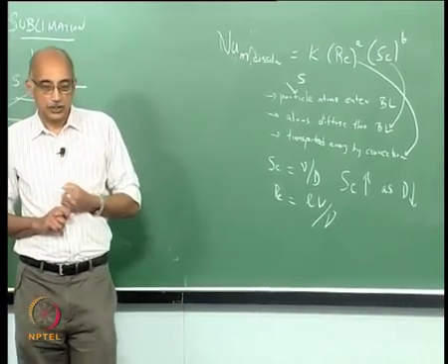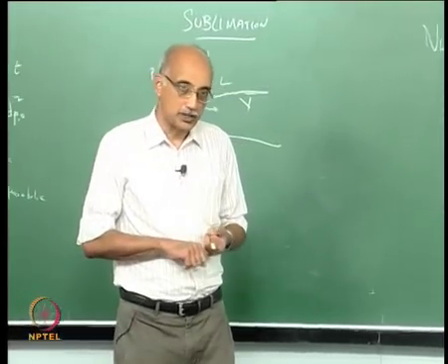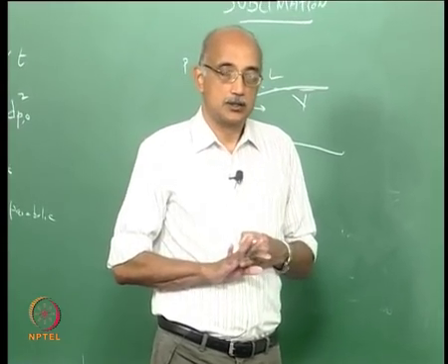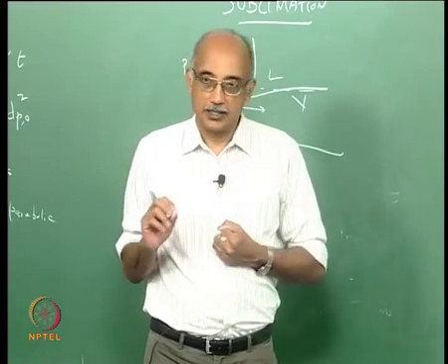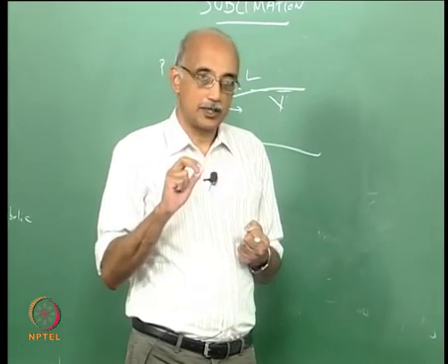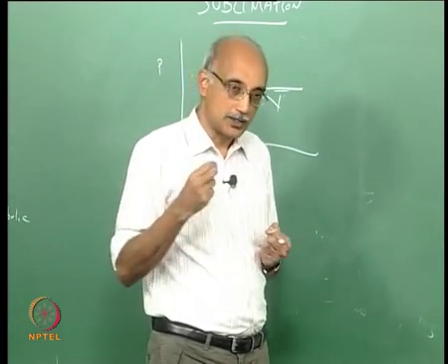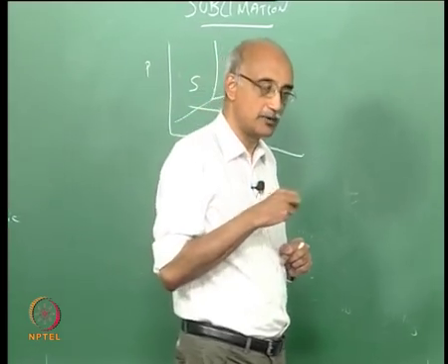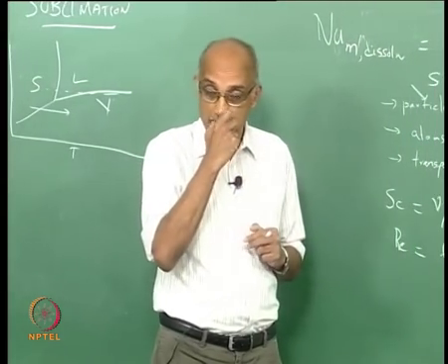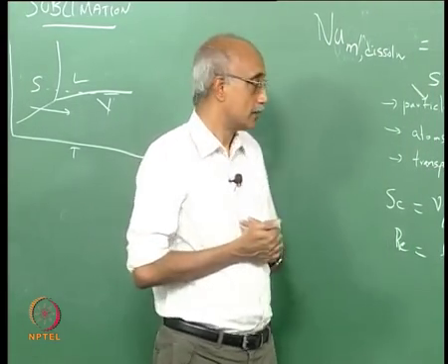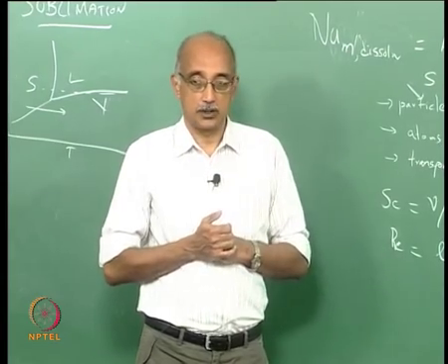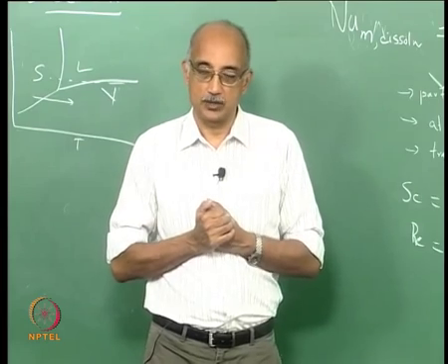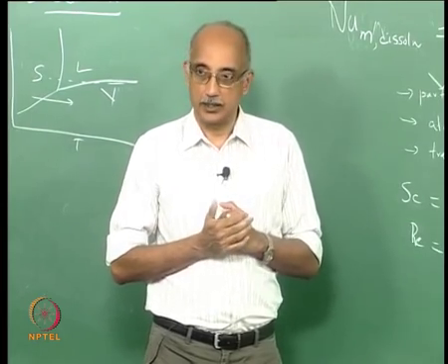Typically both in the case of dissolution as well as sublimation, the Stanton number is not a critical factor, because you are considering typically cases where the flow velocities are relatively low, and therefore the process of dissolution or sublimation is governed by diffusive phenomena. There are always exceptions of industrial processes where the Stanton number or the convective flow can dominate dissolution and sublimation, but it is fairly unlikely.